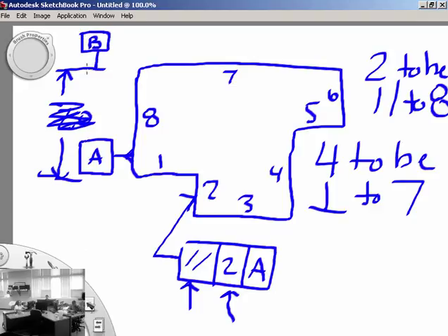Okay? Why do they do that? To keep from cluttering up this space, because there may be other dimensions going on. So you may see datum references attached to dimensions, but they still talk about the same surface. You see how this B still has the little darkened triangle and it's floating right across from this surface? That lets you know that this surface is still that datum, because technically this line is infinite. It doesn't really matter if it's touching the surface or not. It just means anywhere along this theoretical plane is a datum. Y'all see that? Does that work for you?